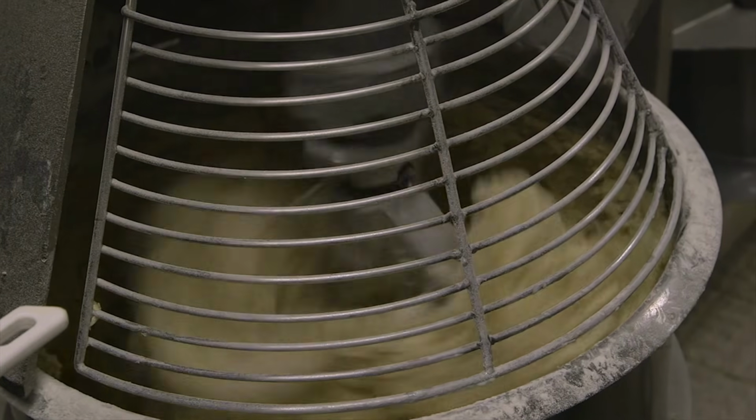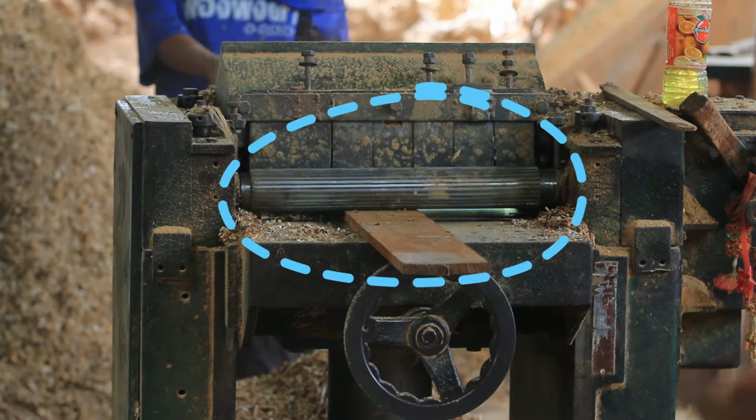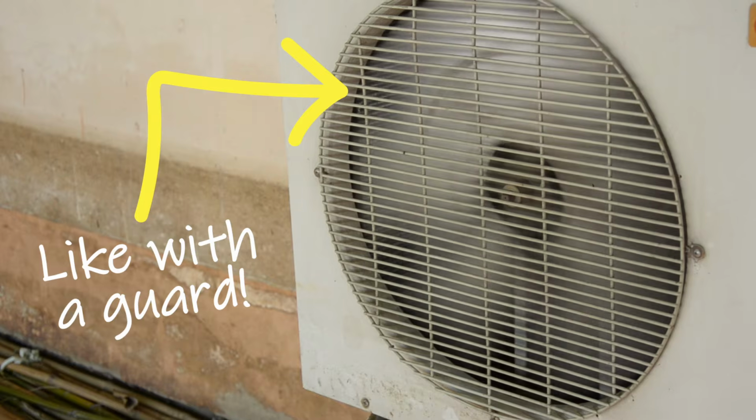Here in the UK, we have a duty to prevent access to the dangerous parts of machines. So I say dangerous parts of machines, could be the electrics, could be the moving parts, the wheels, the cogs, the rollers. We have a duty to prevent access to those so far as is practicable. It means that we have to do everything that is technologically possible to stop fingers from getting in there. Which means if somebody invents a new, better technology, like some kind of sensor, some kind of light curtain, some kind of light beam, something that can scan my genetics and say, oh look, that's a human, I'll turn it off. Yeah, some crazy technology, it means we are legally required to install that.